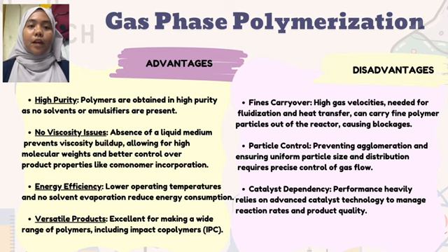For advantages, the first one is high purity. Polymers are obtained in high purity as no solvent or emulsifiers are present. The second one is no viscosity issues. Absence of a liquid medium prevents viscosity build-up, allowing for high molecular weight and better control over product properties like comonomer incorporation. The third one is energy efficiency.